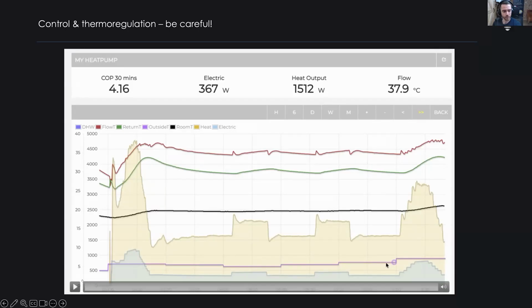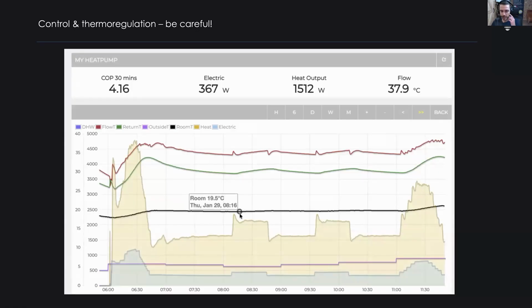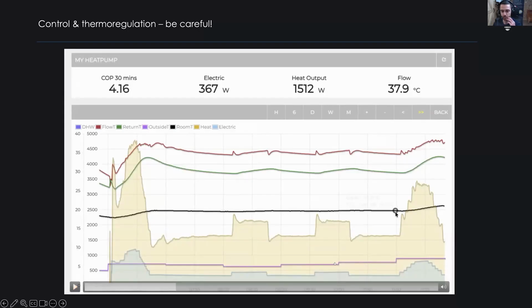Here you will see, I will just start this screen recording, how room influence on controller can have high impact. So you will see here, let's say the outdoor temperature is the same, but at that point, I changed the room influence on controller. So I changed room influence, so indoor temperature will have higher influence than outdoor.